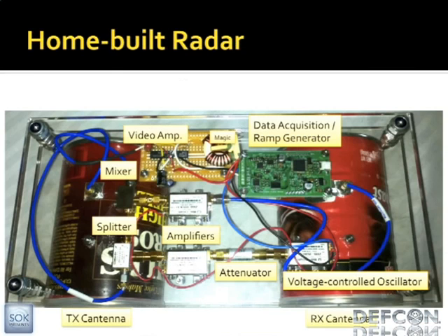Oh, so the reason that's there is because I was trying to make this thing USB powered, so I just wired it onto the power for this other stuff. Everything on here runs off of 5 volts. So I plugged the USB in, and the computer doesn't like that. It just turns off the port. The problem was the inrush current was too high, and I needed something to slow that down. So I was like, okay, I'll put an inductor in there. And the only one I could find was this big choke transformer thing. So I just shoved that in there, and that worked. So that's all that's for.